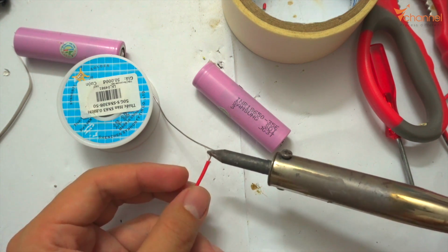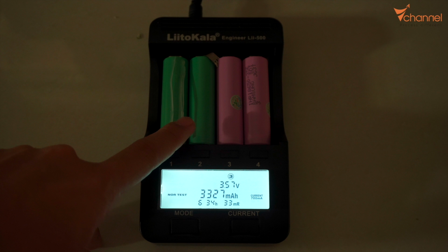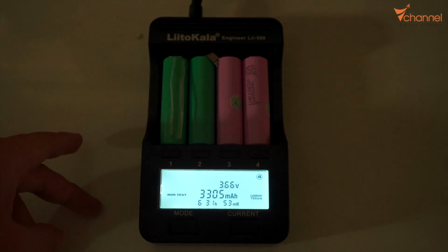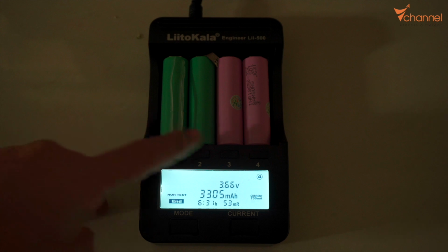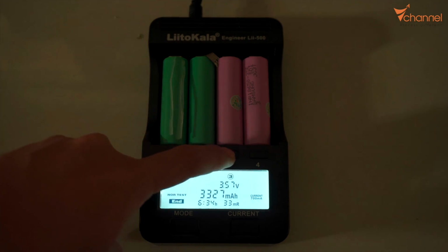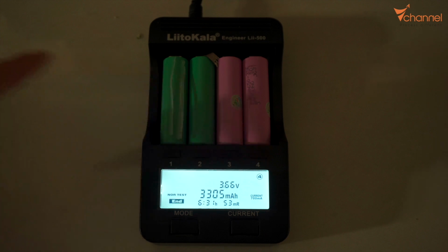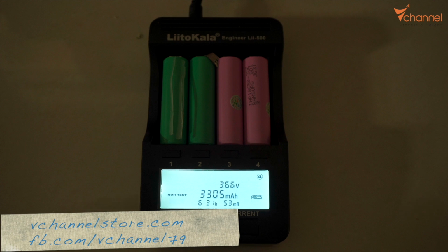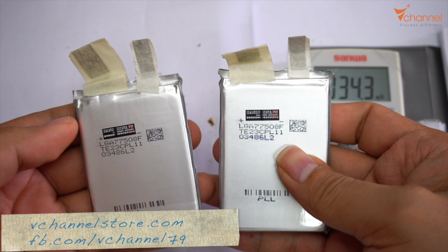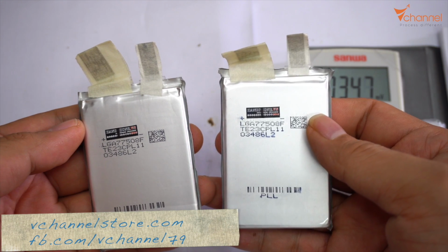The real capacity of this cell is just 3327 mAh, and the next is 3305 mAh, not reaching the 3500 in the battery information. The internal resistance is 33 milliohm, and the second one is 53 milliohm. Not so similar, however the difference is not noticeable, but apparently the real capacity is quite a bit smaller than the battery information. Next, I use lithium polymer battery cells from the Mavic Pro.